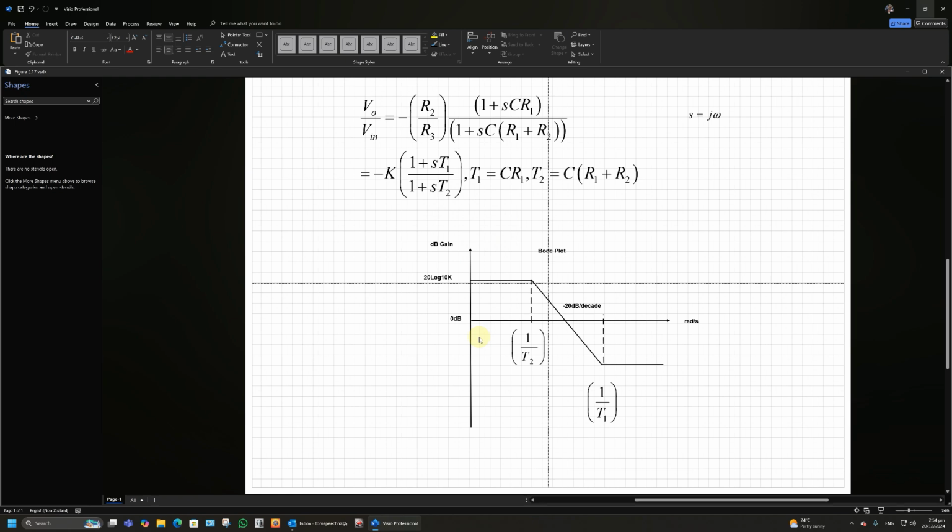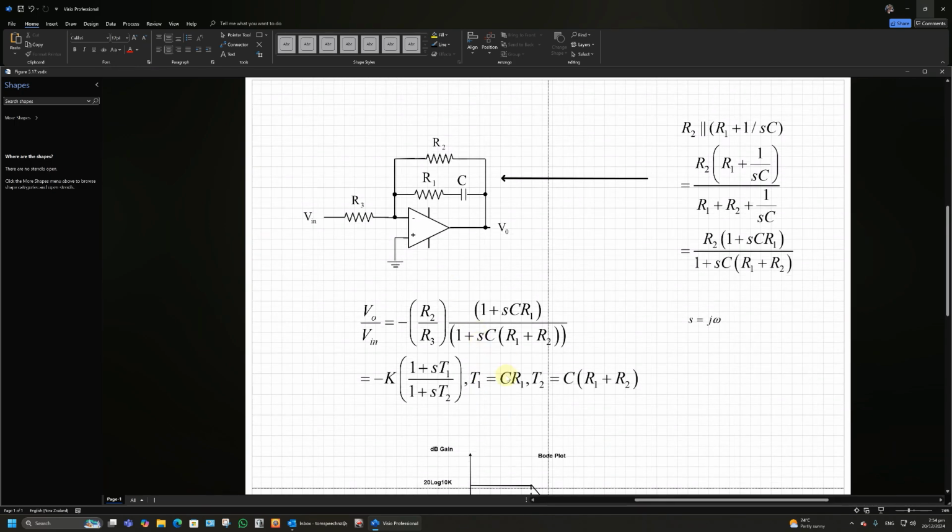Sometimes you can't put in pure integrators in circuits, and so you're sort of stuck with this kind of phase lag thing. In phase lock loops, sometimes they have lag lead passive networks. This is the lag part. There is a bit of a confusion. Some people call this lag lead because the lag part is the pole, and then this is a lead. But we normally call it a phase lag in control systems. And a lag lead is a combination of this circuit with another circuit, which is the upside down version. As I say, what happens is you take all of this and you put it in here. You swap R3 with all of this, and that becomes the phase lead or a phase advance.